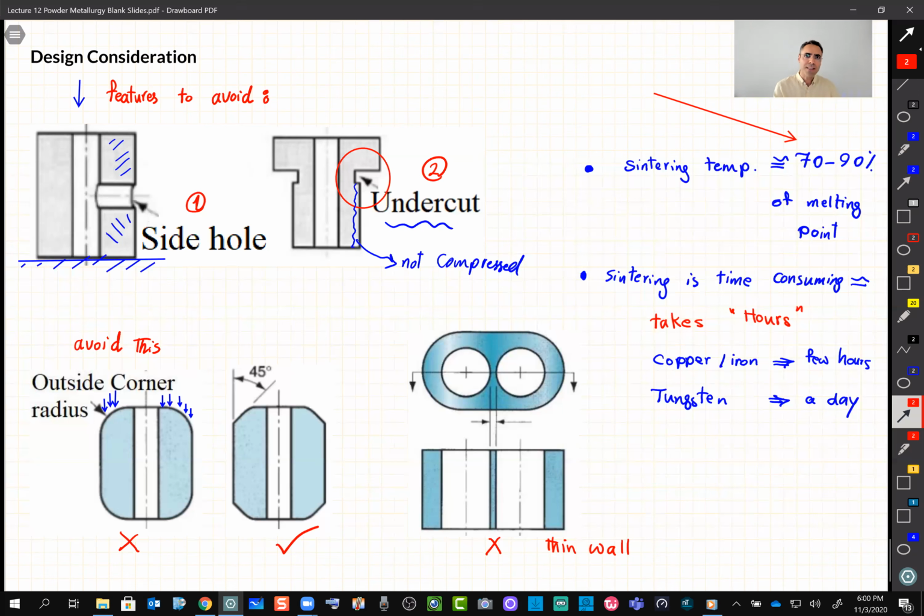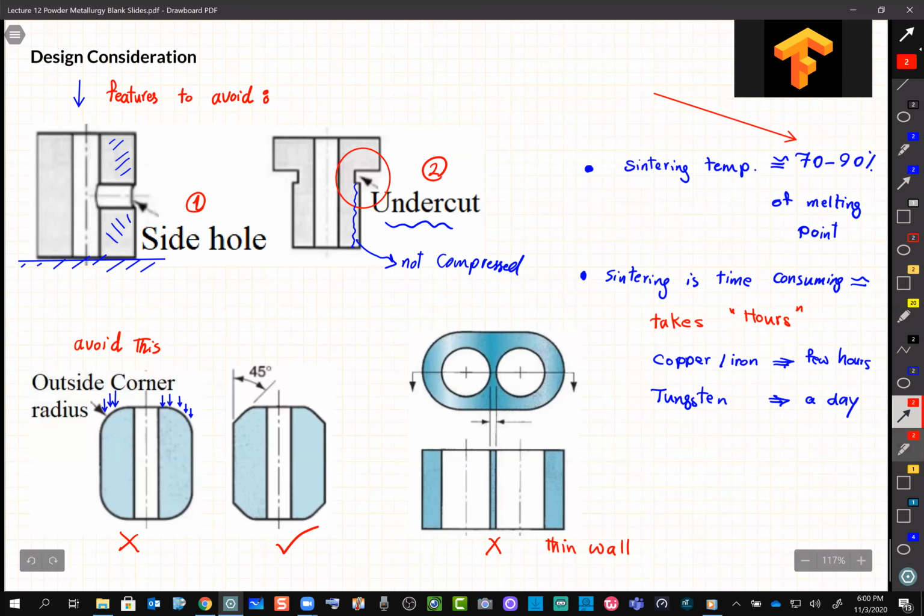The lower melting particle is going to act as the binder. Sometimes people even use plastic as the second material. They use powder plastic and a metal, mix them together, compress them, and then put them in a furnace. The plastic melts and creates that binding. It is cheaper to melt plastic, right? Does that make sense, Jesse? Yeah, that makes sense. Thank you.